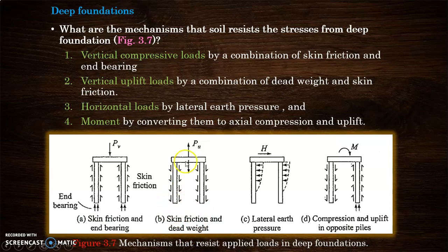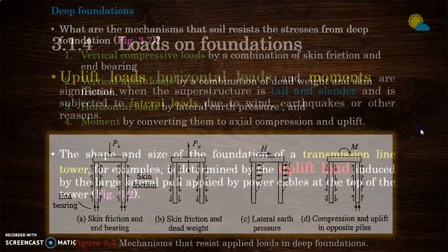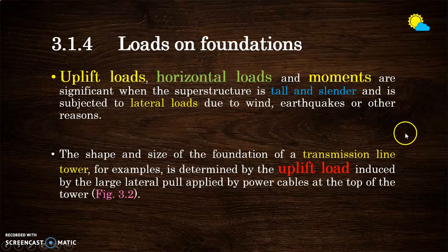You also have the dead weight of the foundation itself, of course, because at the top you have your pile caps, and you could have lateral pressure coming in and also moments. So you can see there are similar loads as for your shallow foundations. Now, this is one that is interesting and important: the uplift forces, horizontal loads, and moments.